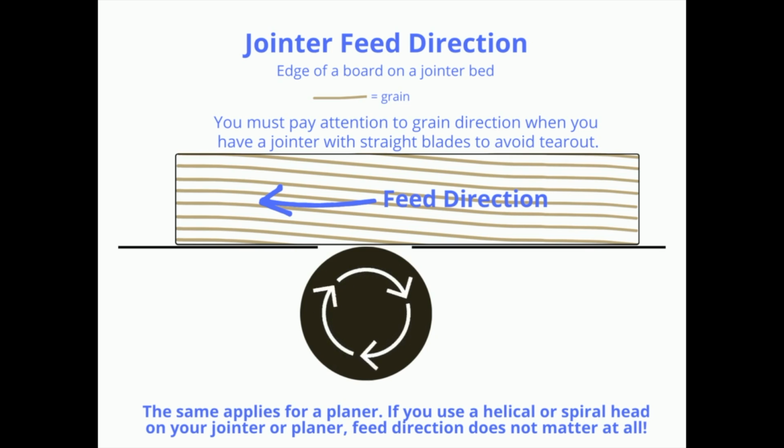A quick note about feed direction. If you have a jointer or planer with a traditional 2 or 3 knife system, you'll have to pay attention to feed direction. Otherwise, you'll get a lot of tear out if you feed in the wrong direction.